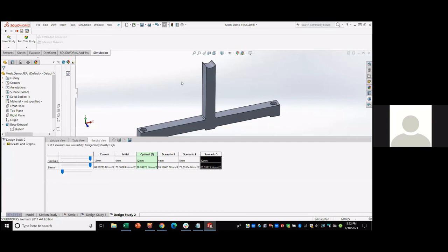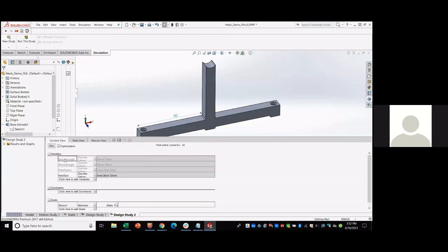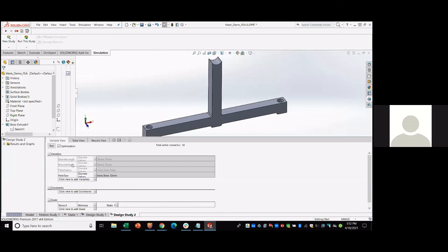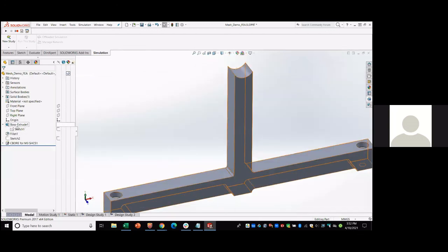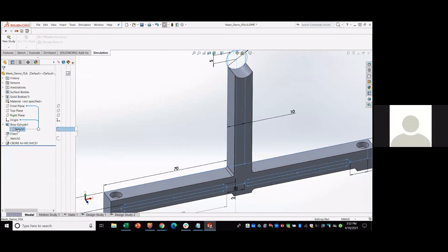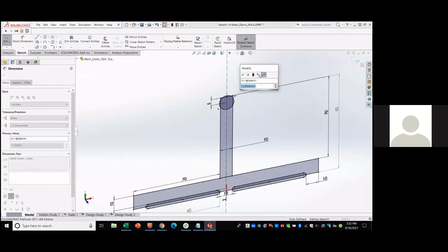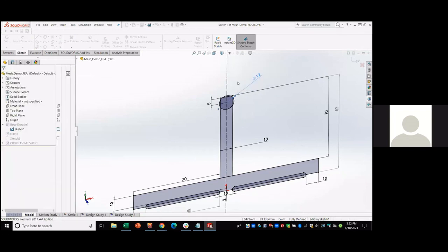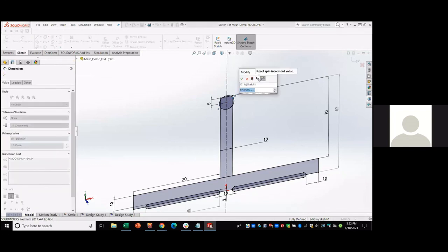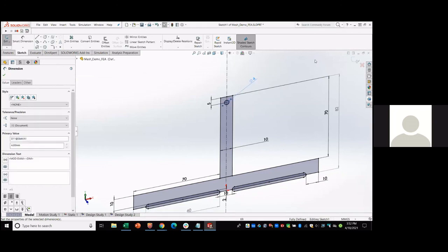Okay. So one point about the parameters that get linked into your models here. All of these parameters, if I go to the variable view, bracket length, bracket height, fillet radius, these are now controlled by the design study. If I go back to my model, I can change this, right? That's not a big deal. So just make it 4 millimeters and it goes back.